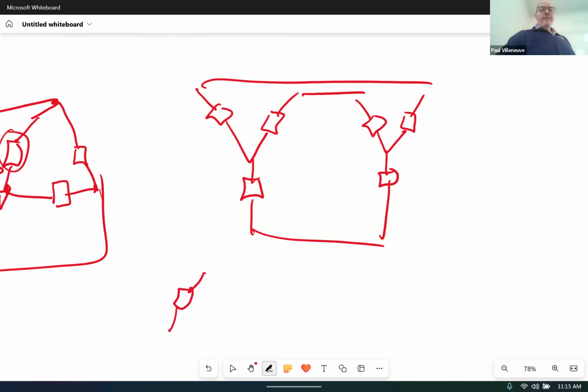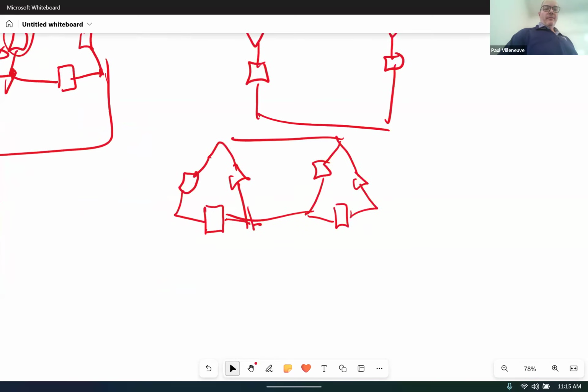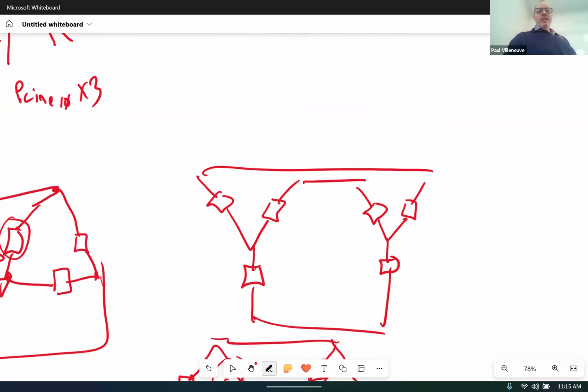Or, nope, you did this. I can see that this one is definitely in parallel with this one. And over here, is this one in parallel with this one? Are these points electrically at the same point? There's no wire between them, but remember in this class, everything is balanced. So this is at 0 volts and that's at 0 volts. Electrically speaking, they're at the exact same potential, which means they are in parallel.